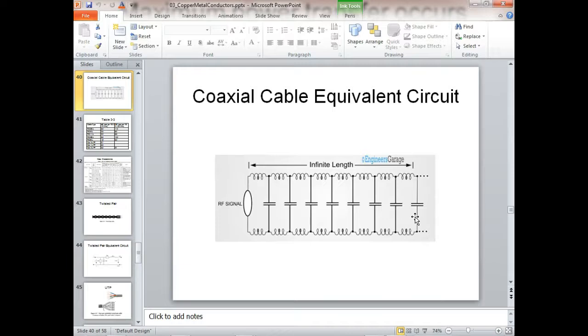And I think Charles was talking about how he got an old 300 ohm antenna, but he's running it into a 50 ohm input. Well, what you do is you get a little transformer. It's called an impedance matching transformer that is matched for what? 300 to 50 ohms or whatever you run.